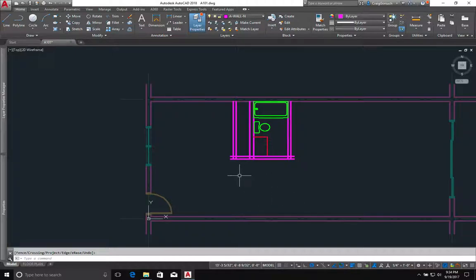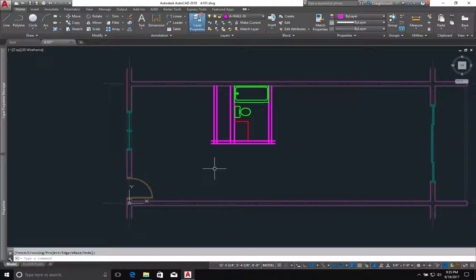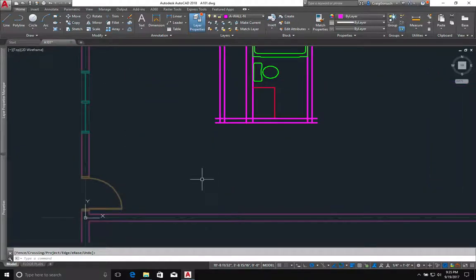Now, one of the things I mentioned is that we need a minimum of 5 feet for corridor clearance. Technically that's a commercial construction thing. Some of those standards might apply in an apartment complex. Not to mention, having 5 feet is really super open, a comfortable wide corridor to go through. So let's see if I can do this. Offset 5 feet. No, it won't let me use that as an offset distance. So I'll just draw a line from here down to there.